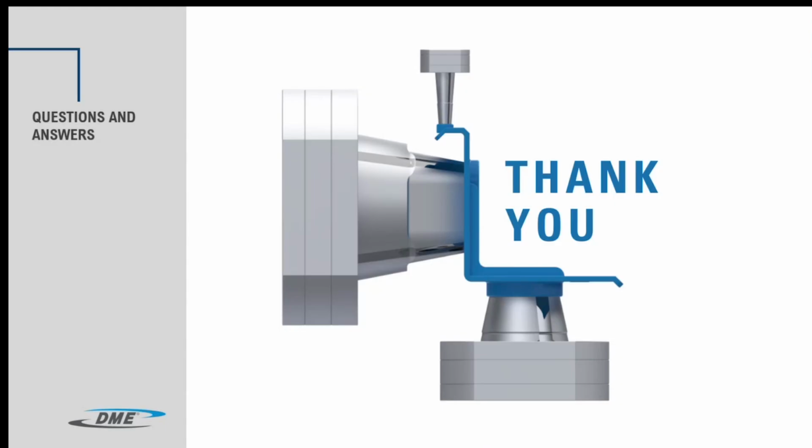Okay, and again, everybody, if you have questions, please put them in the chat. We have another question: what is the rough cost comparison with servo-driven unscrewing molds? Generally speaking, in upfront cost there can probably be some savings using a collapsible core. Certainly, it's a simpler mold design. Long term, over the life of the mold, the collapsible core is going to be much more cost effective to maintain than an unscrewing system.